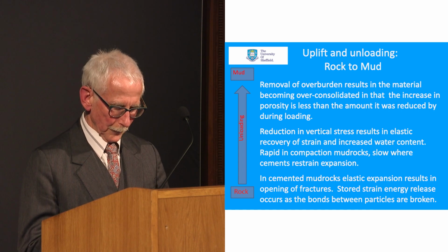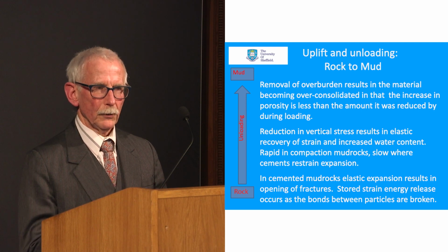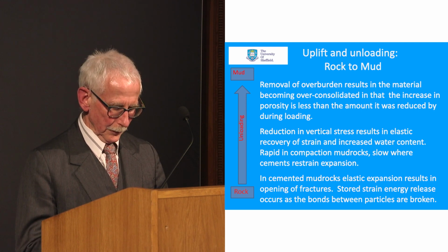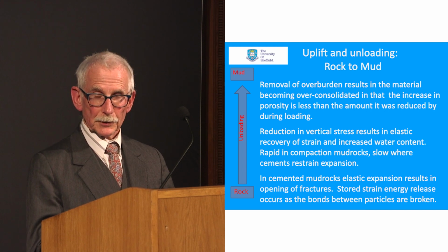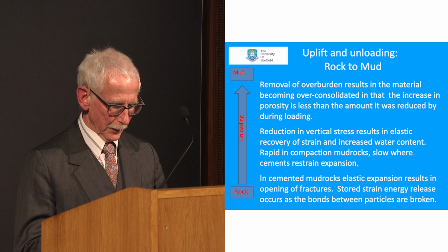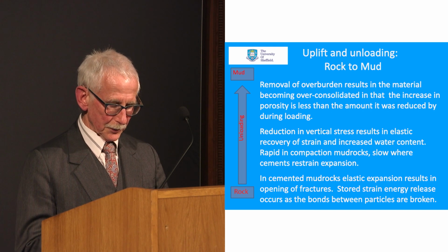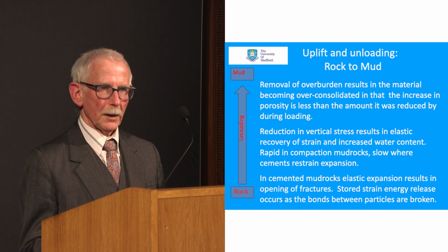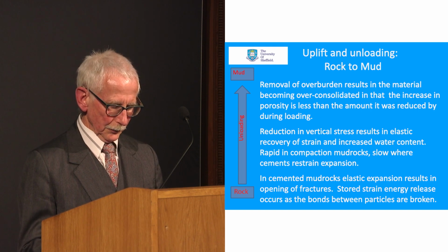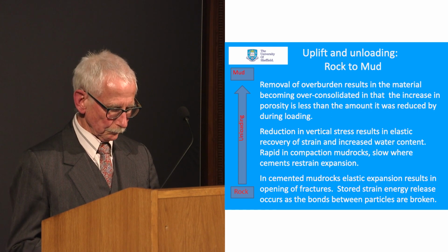This process of wetting and drying, therefore, is very damaging to mud rocks and will lead to their breakup, both because of the effects on the clay minerals causing them to expand and contract and this process of air breakage. Some mud rocks have undergone phases of burial and exhumation, which will introduce other structural and mineralogical changes, and we need also to take into account the glacial loading and unloading and periglacial effects during glacial periods.